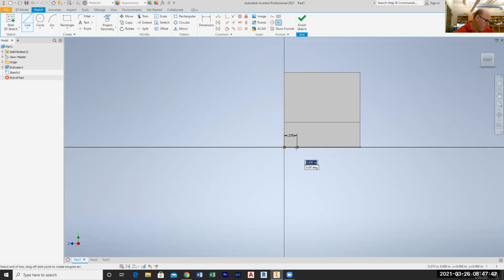Okay. Now there's an angle that goes up at 60 degrees, okay? So let me just go this. Rather than know the distance, let's go, what's that going to be, 60 degrees. If I go from here up 60 degrees, that is 180. 60 is going to be 120, okay? So I'm going to hit Tab, and I'm going to hit 120, enter. 120, okay? It's 120, but this distance right here is 60, okay?